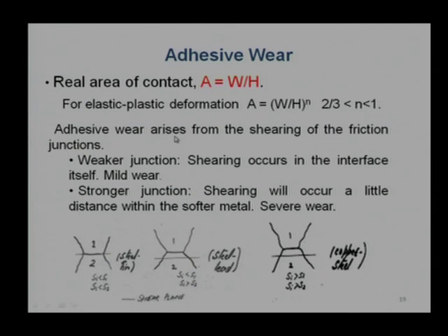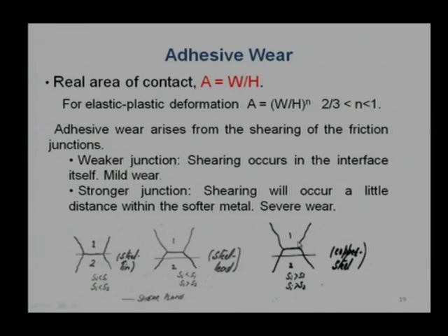Shear strength is higher, and it will be unpredictable whether the steel surface or the copper surface is going to lose material. It may be randomized. Where there are more high-magnitude asperities on the steel, with more cantilever length, naturally the asperity will be plugged out from the steel surface. If the asperity height is very high on the copper, that surface will be worn out.